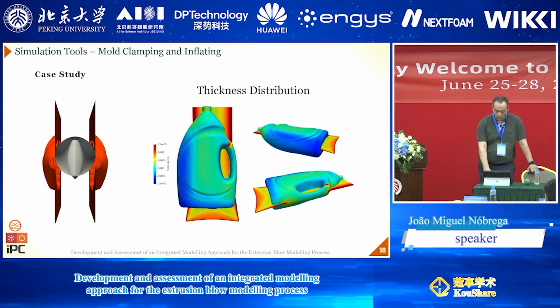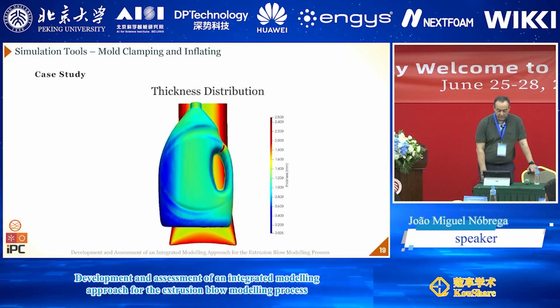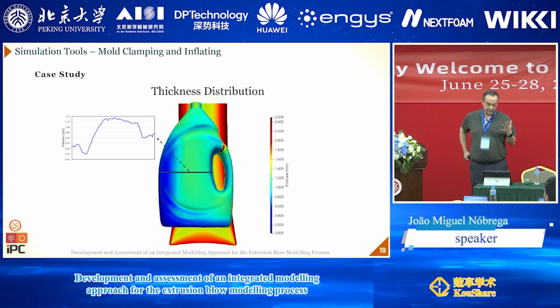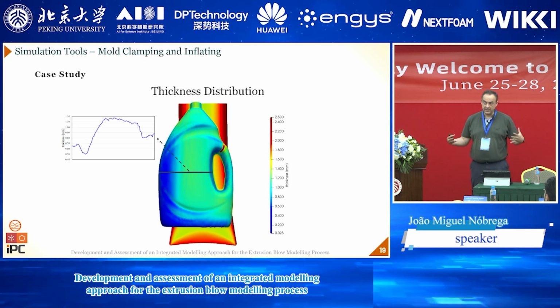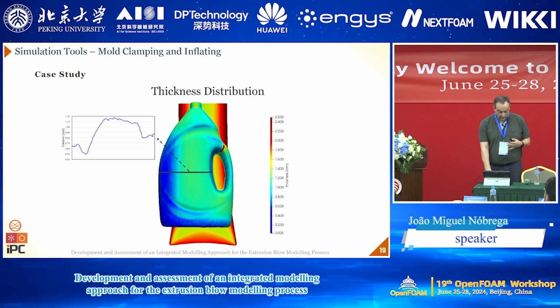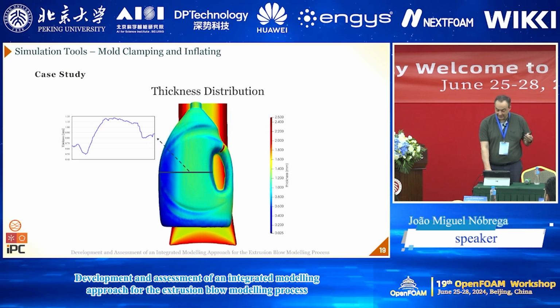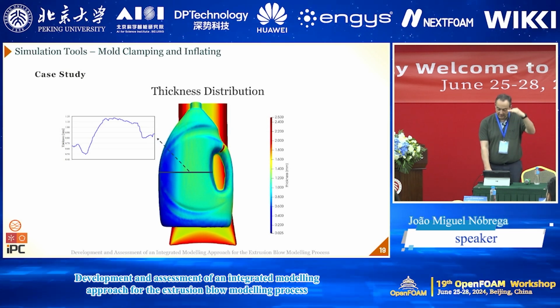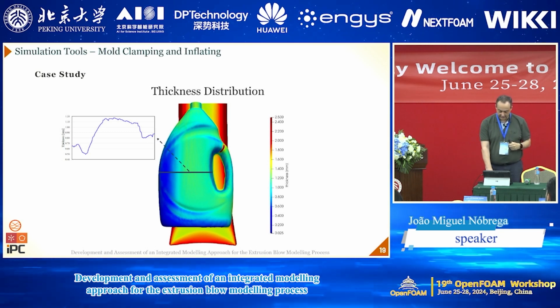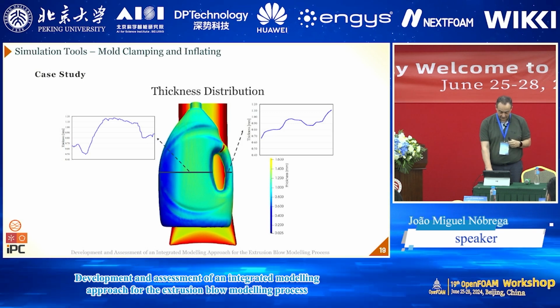And this is what we can get. Obviously, one of the important details in terms of calculation is the thickness distribution we obtain for the final container. That we can measure, control, and then adjust, for instance, the thickness of the parison along its length in production.